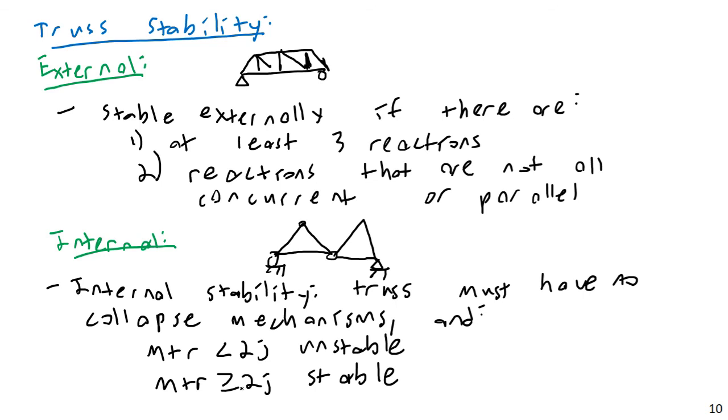But you can very easily end up with a truss, if you're not careful, that is statically indeterminate, even though it is stable. It's just, we can't solve for all the forces, at least using only the laws of statics, but that's the idea. Okay. Questions on that? Okay. Finally, I'd like to discuss the definition of a simple truss.